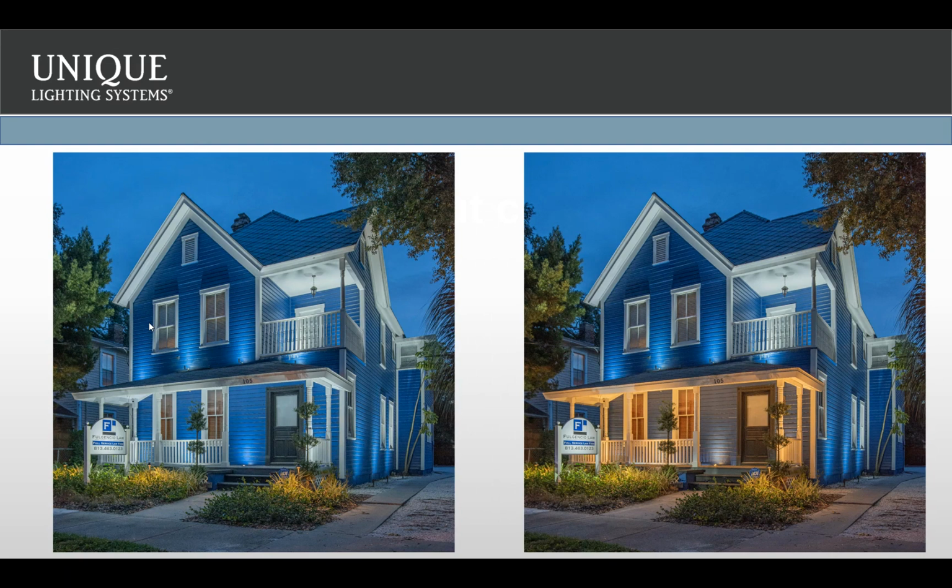Rather than trying to pick a color in your head and saying all these trees get 3000, all those trees get 3800, you can go to each lamp and slide the slider bar to a color position that looks good to you, or to your client, which is more important, of what color is comfortable for everybody. Once that's set, it stays that temperature until it's changed again.